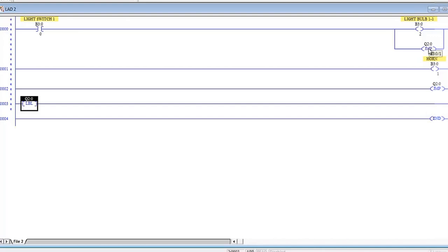So they have all these jumps with conditions, but they don't have a jump all by itself. So if none of the rungs with conditions are met, this line with whatever instruction might be to the right will never execute. So very important to remember that if you're using labels, you must jump to that line or it will never execute.